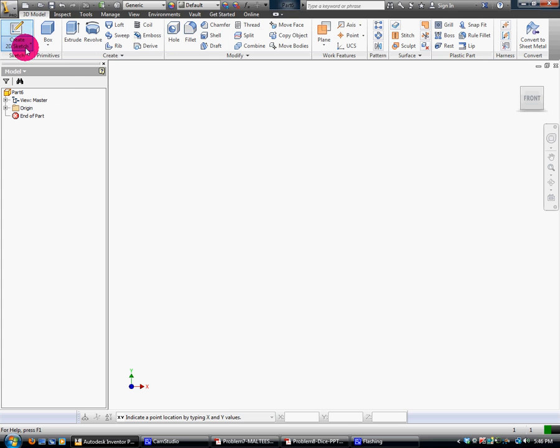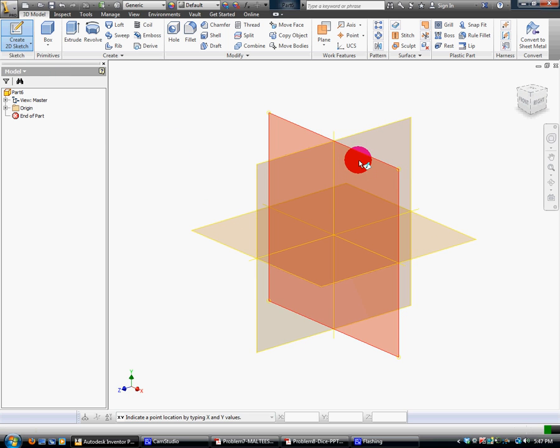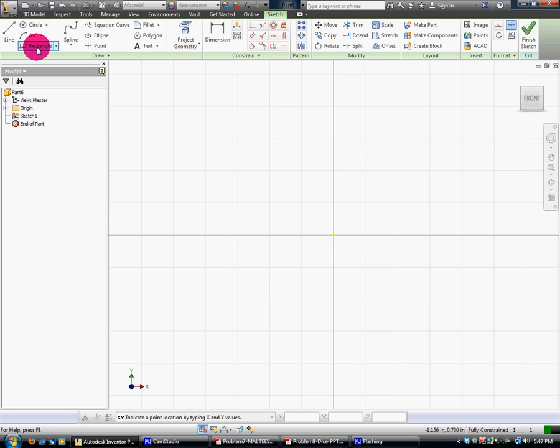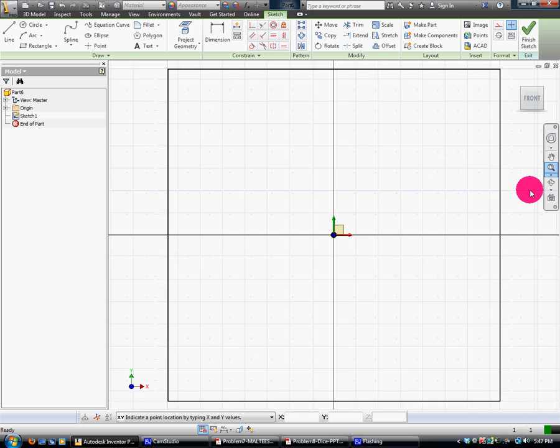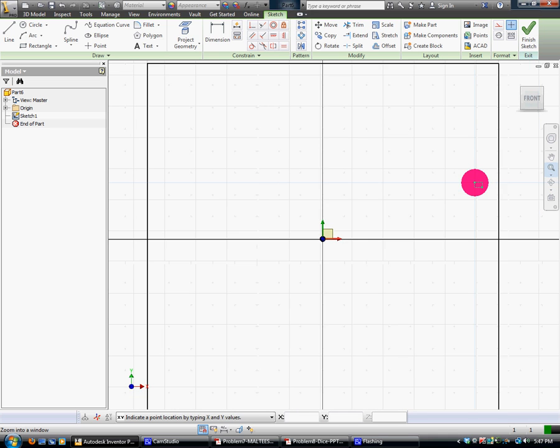Alright, and I'm going to create a new sketch again. And I'm going to draw a rectangle. Now, again, everything that I'm doing is in the PowerPoint, so I'm not getting this from just anywhere. If you follow the steps in the PowerPoint, here it is. I want a perfect 2 by 2. So if I know perfect 2 by 2, I can do a little math there, and I can go, okay, well, -1, think back to your coordinate systems, your x, y. So x, y, -1, -1, enter. 1 tab 1, enter. Come right here and do a zoom all, and you have a perfectly squared rectangle.